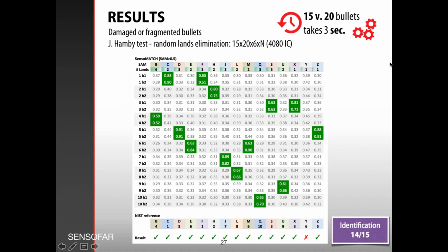And for the outliers, the filtering: the filter that removes the surface roughness is a waviness filter, or in other words, a filter that removes the highest frequencies. It takes out the outliers from the surface. So in the characteristic surface that is filtered, we don't have significant outliers that would make a difference for the final score.